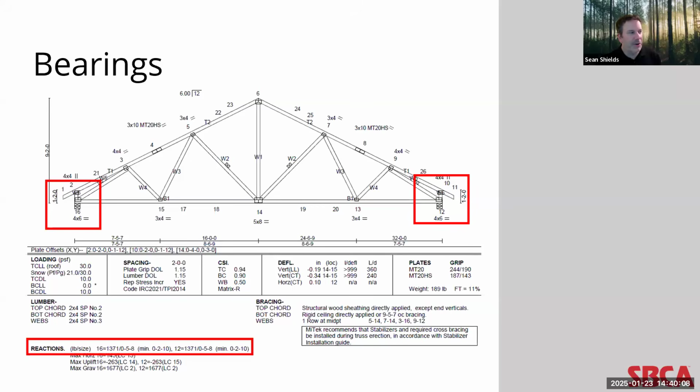There are other issues surrounding having a wall that's not exactly to dimensions, but again, it's underscoring that you don't have to have that full, in this case, 5.5 inches of bearing utilized, that the truss, again, will still perform without problems like fiber crushing and that kind of thing, all the way down to 2 10/16 inches.